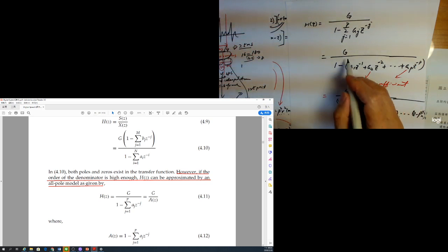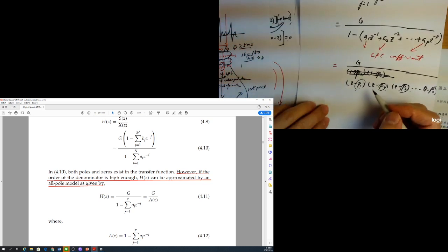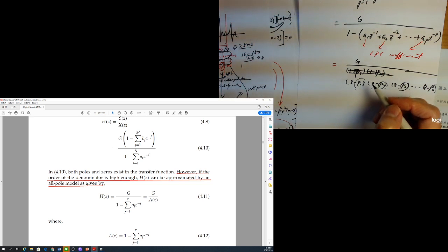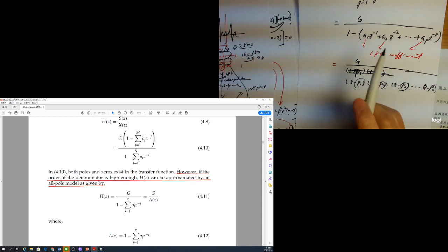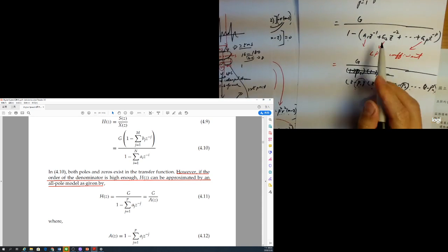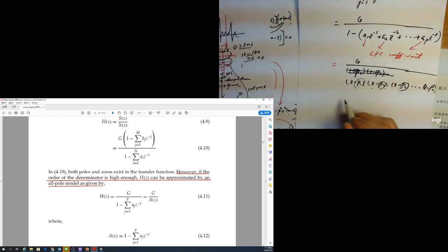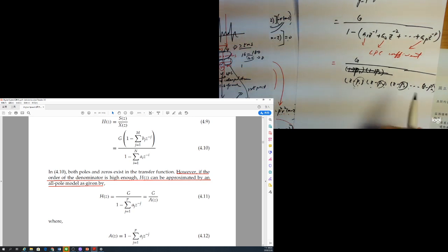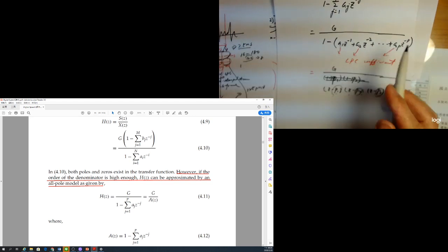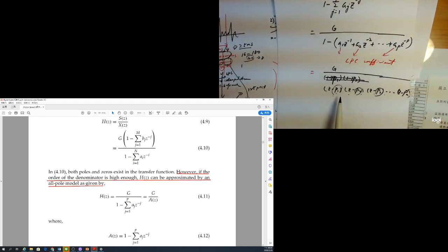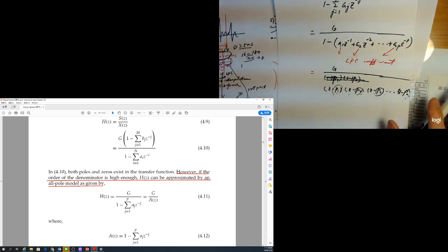So this is the Z transform. With the Z transform, to be stable, the poles should be inside the unit circle. The S domain is the left hand side, but in the Z domain you have to make sure your poles are inside the unit circle. Because we get the coefficient and then do the quantization, the poles of the open model should be inside the unit circle, so there is a stability issue.